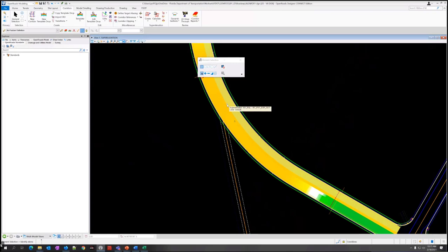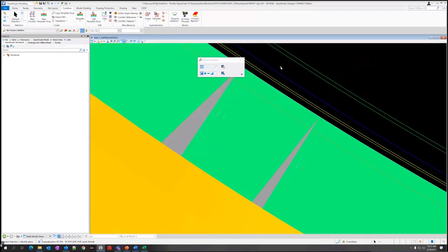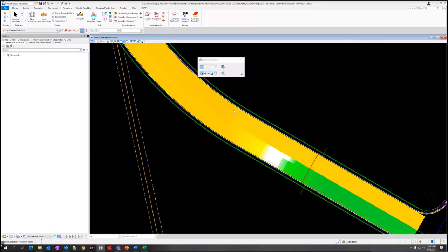But it goes to, I think it's like 3% or something. It should show if you select it. I think it's 2.4. This is why it's not very noticeable. So it goes right here to 2, and I think it says 2.4 right there. So we'll open the super elevation editor and look at that some more later, just so you understand what these are. Okay, so that wraps up exercise 3.3. So we skip down now to exercise 3.6 because the next two are the ones where you do it manually. Don't need to do that because we've done it here.